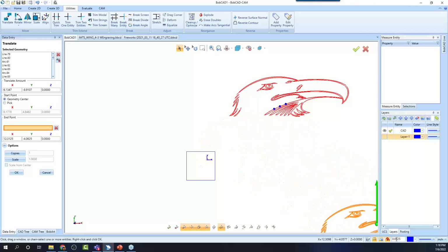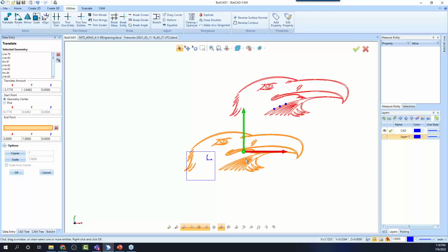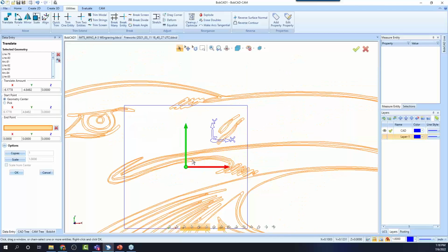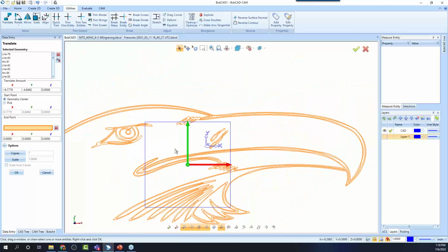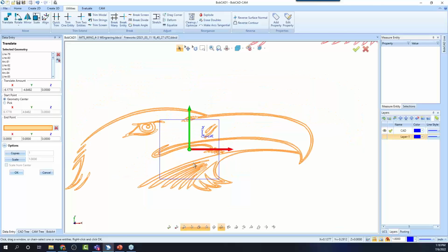So what we want to do is go over to our snap grid here and make this a much larger number. I'm going to make it 1 inch and then enter. Okay, so now every time it moves over, that's a 1 inch increment. And I could use this to help me size up where I want it to go and to be able to move it around a part or a line, the center of this geometry to the center of another piece of geometry.